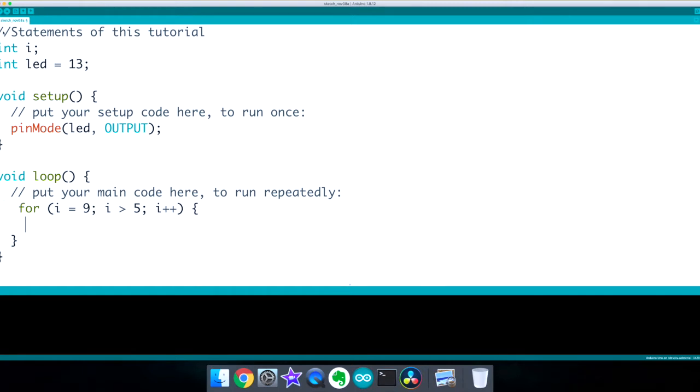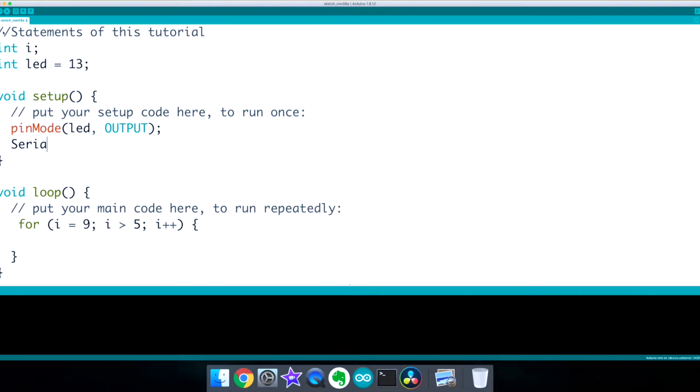So we're going to be doing a PWM. If you don't know what that means, it's pulse width modulation, or in an LED's case, the brightness can go up and down. There are not that many pins that can do it: pins 3, 5, 6, 9, 10, and 11. So those are the only pins that'll work with PWM.